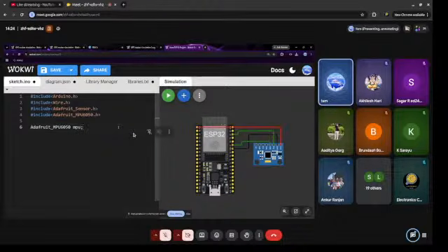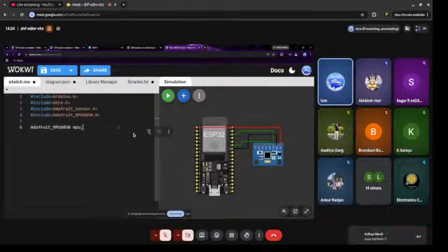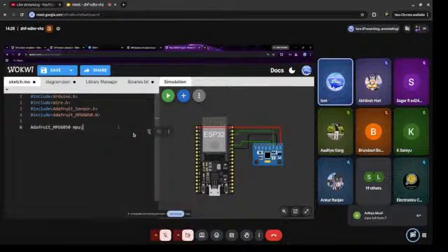This line is creating the sensor object. This creates an object that is called MPU. Think of it like creating a remote control for the MPU6050. Using this object, we can do things like initializing the sensor, change sensitivity, read the acceleration, and read gyroscope values. Example: MPU.begin starts the sensor, and MPU.getEvent gets the data. So from this we are creating an object that is called MPU. Did you guys get it?